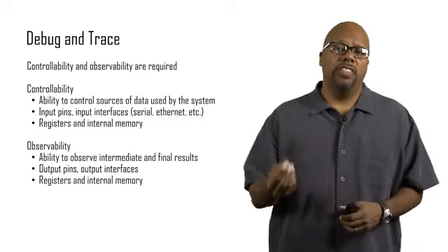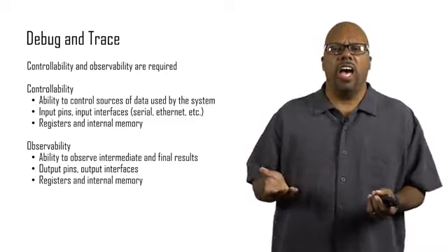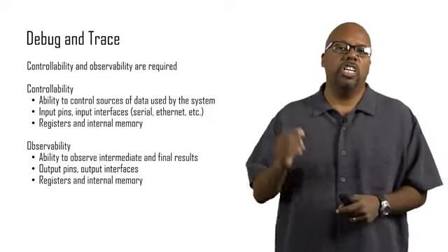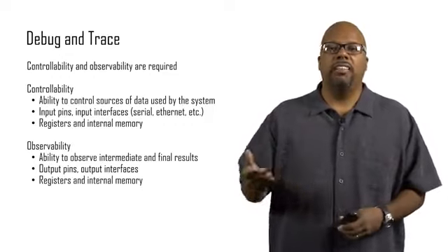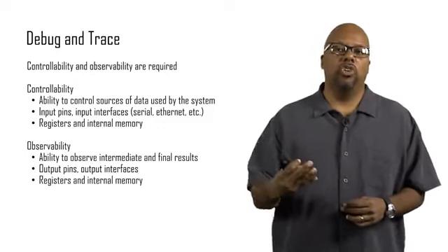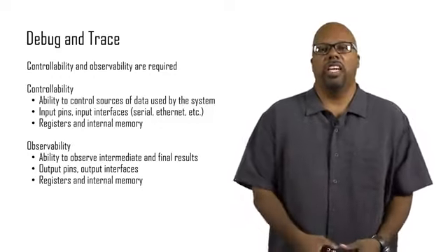So if an output pin changes slowly over time, then a multimeter is fine, right? Multimeters are changed slowly too, so that works. But if the signal is changing fast, say every millisecond, you can't see that on a multimeter. You would need to use an oscilloscope. An oscilloscope basically shows me the voltage over time. So you'd wire it to an oscilloscope, and you can observe the data that way.